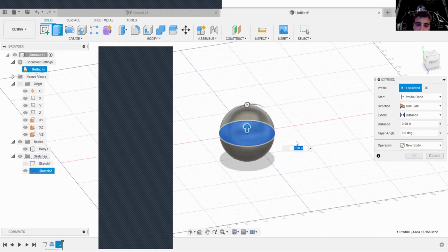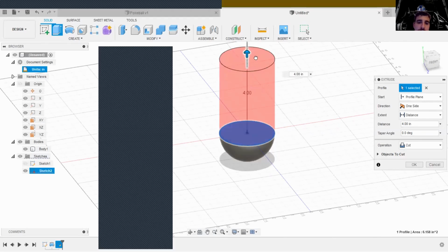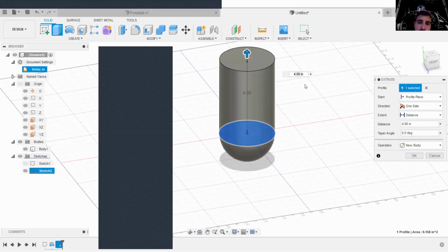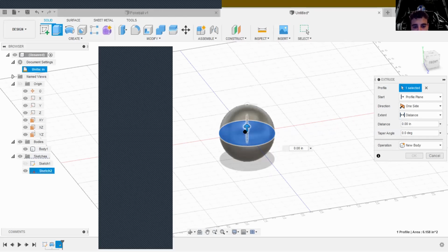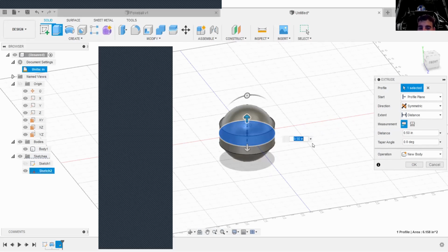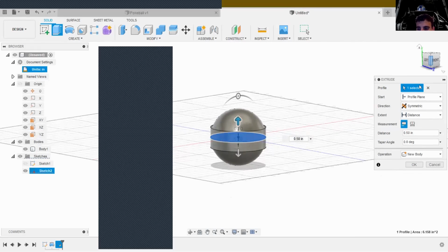One example, which we're not going to do, is you can make a cylinder out of it. It makes that kind of cylindrical shape, but that's not what we're going to do today. What we're going to do is use it as a cut feature. So we selected our profile, and we're going to have it propagate in two directions because we want it symmetrical. So symmetric, two directions. And then the distance, let's see, what should the distance be? 0.2? I don't know.